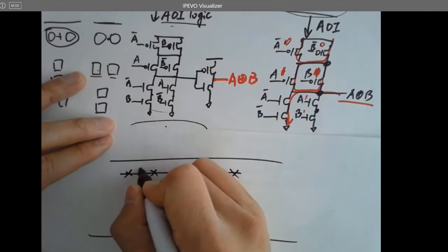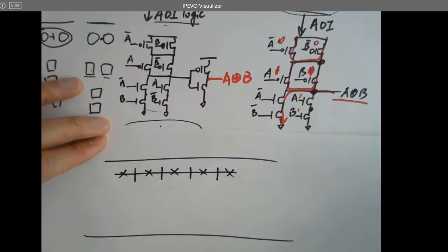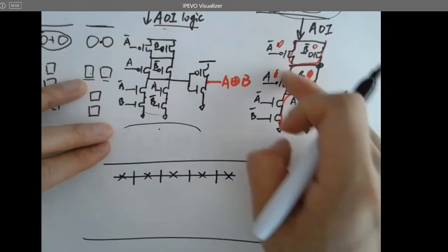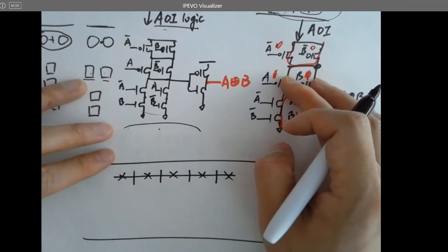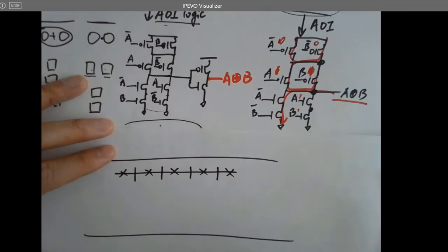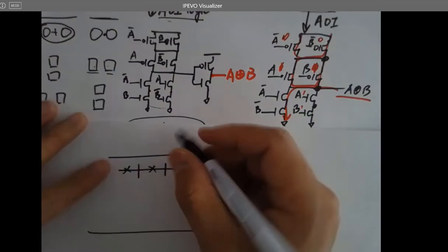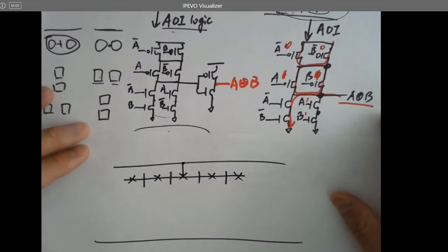The two are in parallel, so these are the gates, right? This input signal. Two in parallel, and then in series with another two parallel PMOSes. There might be multiple ways to do it, but let me just do whatever I have done here. I guarantee it works. If I draw a VDD signal from the middle, like this,